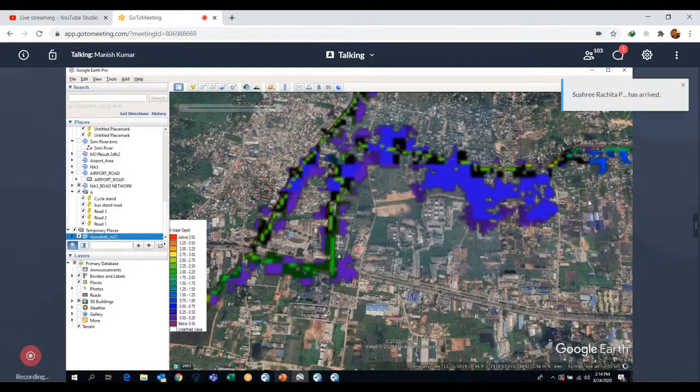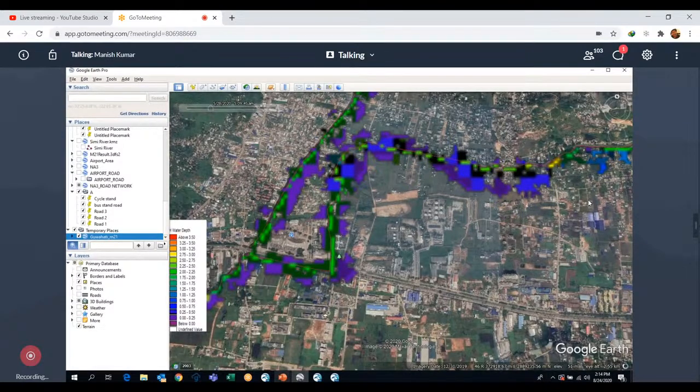This information is very important. This is not historical information, but it is based on an inflow forecasting system. An inflow forecasting system is where you have a 1D river model and forecasted precipitation information. You get forecasted precipitation from agencies like IMD, NCMRWF, GFS.